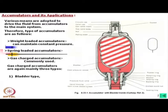Now, if we look at the bottom side, there we will find the pressure fluid valve. So, there is another valve through which the oil is allowed to the main system, and then this is a vent screw. If some bleeding is necessary, it is done through this.